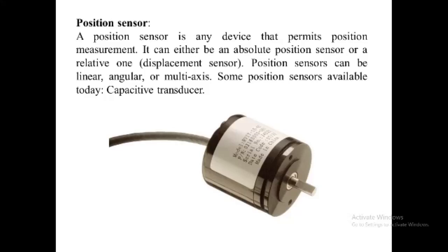Most types of potentiometer use carbon film for their resistive track, but this type is electrically noisy and also has a short mechanical life. Wire-wound pots are also known as a rheostat, in the form of either a straight wire or wound coil. Wire-wound pots suffer from resolution problems as their wiper jumps from one wire segment to the next, producing a logarithmic output resulting in error in the output signal. These too suffer from electrical noise.